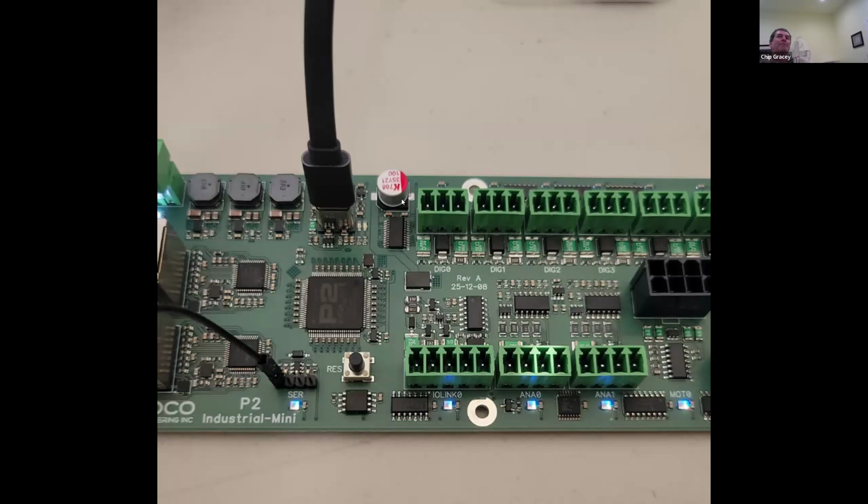And I think what I'll do in the next revision, I'm going to bridge that Schottky with like a 10K resistor so that it can still handle any transient back EMF from the loads out on those digital IOs. But when the rest of the board draws the 24-volt supply side down, it'll pull that cap along with it, rather than just have some cap that goes always to ground, so you're always burning power. I think I'll just bridge the Schottky because now, you turn the power off and minutes later, there's still 20 volts on that cap.